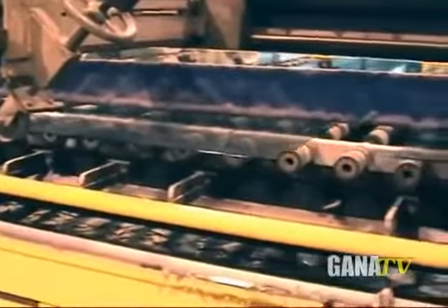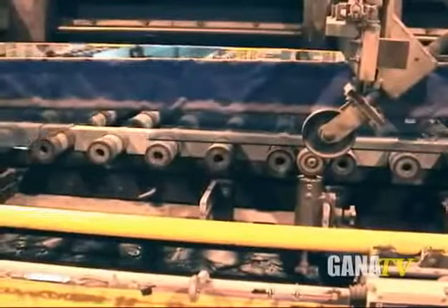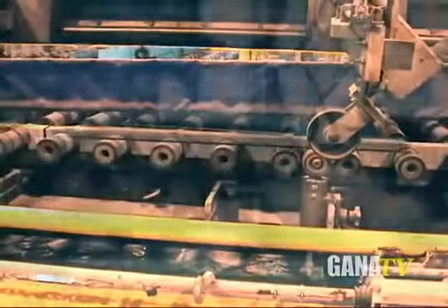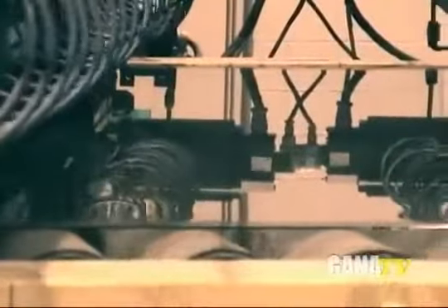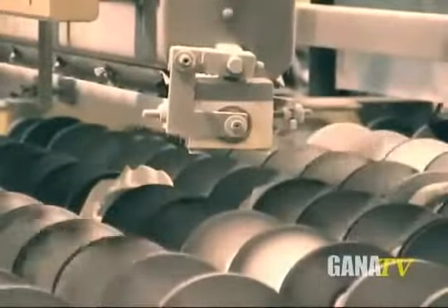The excess glass removed in this process is carried back on conveyors to be reintroduced as cullet into the melting process at the beginning of the line. The glass is transported down the line to be cut into a variety of sizes and go through the edge trim process. The glass is coated by a protective powder which aids in scratch prevention during storage and shipping.